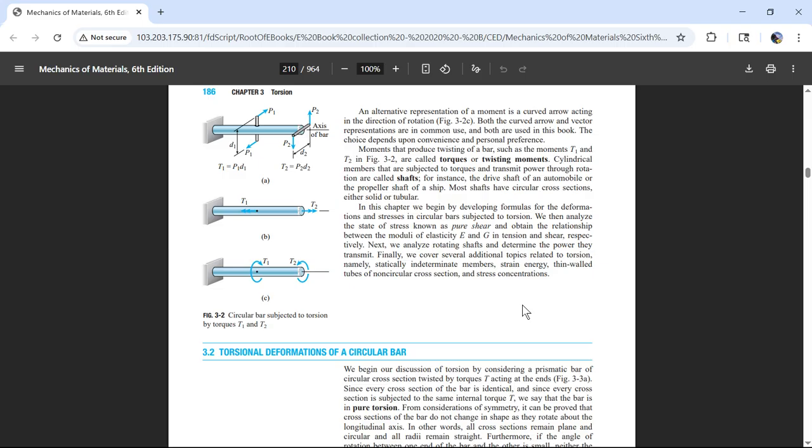0.002 times 1,000 is 2 millimeters. So if I have a 1 meter bar of steel, I just think a 1 inch bar of steel, and I push on it, steel can withstand 50,000 pounds, and both those are synonymous. 50,000 pounds of pressure pushing in on that 1 meter bar is right at the yield. And that thing will shrink by 2 millimeters. So that 1 meter bar will now be 998 millimeters. Cool. And that's where your steel bar gets permanently deformed.